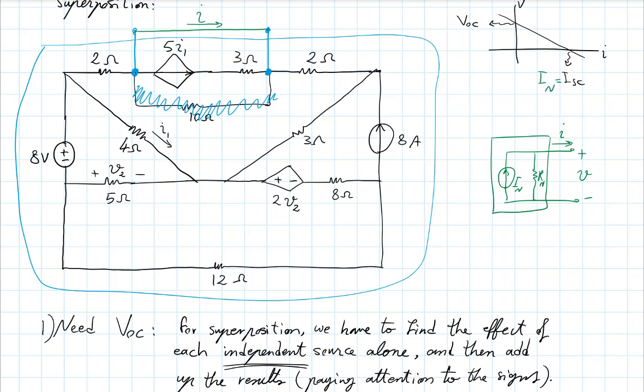Because if you look at the little box that I have up here, the green box, if I short circuit the 2 terminals, it means that the voltage across the resistor Rn drops to 0, so there's no current through that resistor, and the entire current In goes through the wire. So In is simply the short circuit current. And the open circuit voltage, well, if I don't connect anything there, In is going through Rn, and so In times Rn is that.